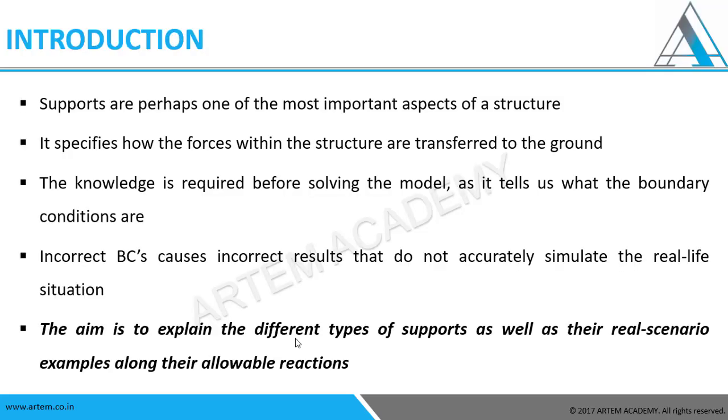Introduction. Supports are perhaps one of the most important aspects of a structure. They specify how the forces within a structure are transferred to the ground. So any component, finally, has to transfer its load to some base, which is ultimately the ground. So what supports are you going to use to transfer that to the ground? This knowledge is required before solving the model, as it tells what the boundary conditions are.